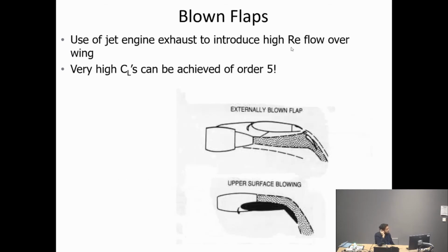Blown flaps use a very similar concept to suction and blowing, really. Here they just use the flow from the engine, the jet engine exhaust in particular, again to energize the boundary layer. And apparently, it's been reported that the CL can be as high as 4.5 to 5.